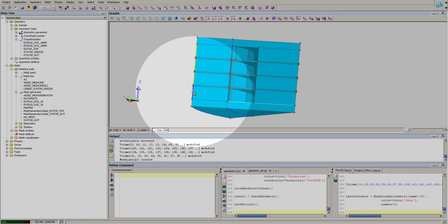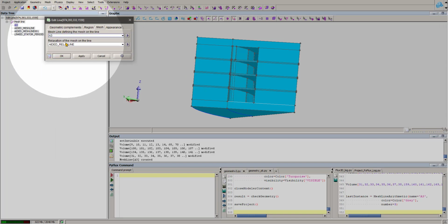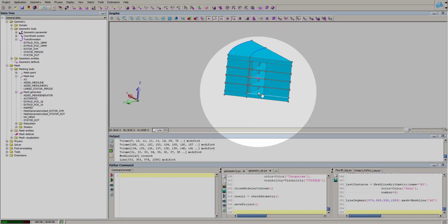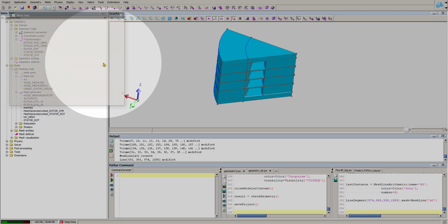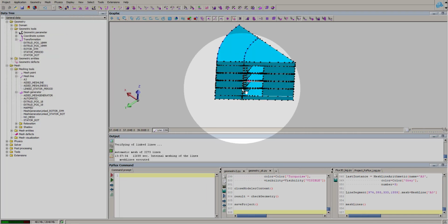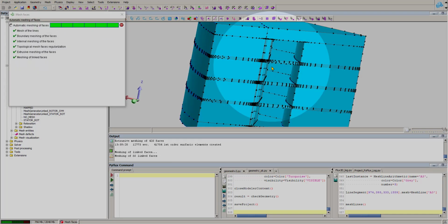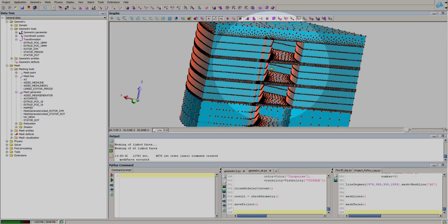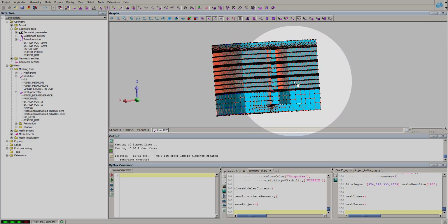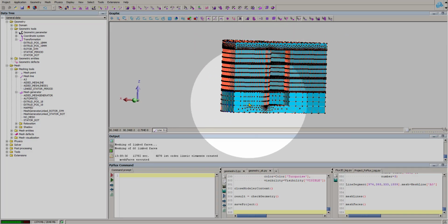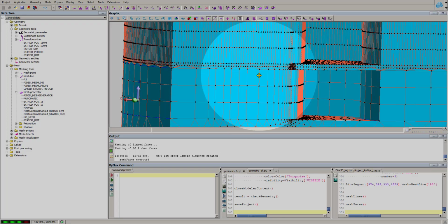once we assign this volume extrusion mesh generator to the selected volumes, we can now create a mesh line and assign it. It's enough to assign it on one line of each layer. Here we created the mesh line of 2 elements arithmetic, so we can see that it creates only 2 elements. But in the first layer, actually there is an issue.